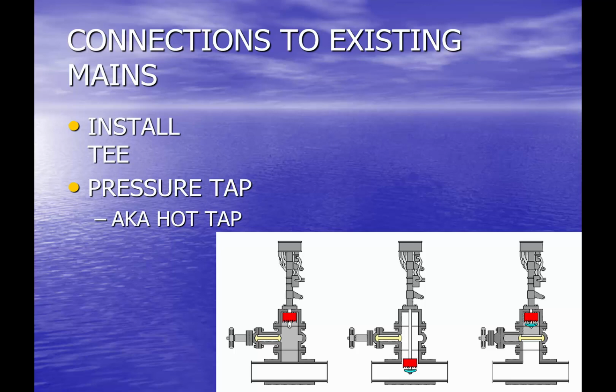It works very well. The only challenge you can have is what size. So for example, if the line that you're trying to connect to is an 8-inch and you want to cut an 8-inch connection in, that's a bit challenging because you're removing so much of the existing pipe. But with a tapping sleeve that is a fully encapsulating sleeve that'll provide structural support given the portion of the pipe that's been removed, that may work.